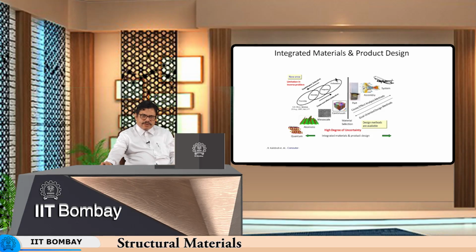So, again here you have cause and effect analysis methods, and if you go backwards, you have the goal oriented design method, because your goal is to fly, and for that you need an engine which is able to generate a certain amount of power, and so materials which will withstand certain temperatures at certain pressures have to be chosen. So, your turbine blades or turbine discs and many other high temperature parts, the combustor parts and so on, will have to be chosen to be assembled together.